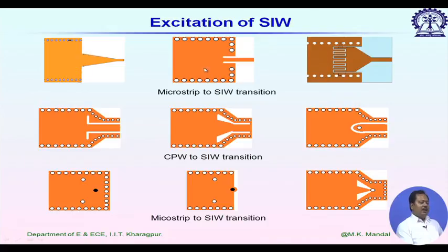Similar design is possible, and on the right hand side, instead of open circuit here, they start with a short circuiting wall. So, it somewhat looks like how we feed a rectangular patch antenna. It is using some inset feeding, and the rightmost one, instead of just simply inset, is actually capacitively coupled. We are using a one finger type capacitive coupling.